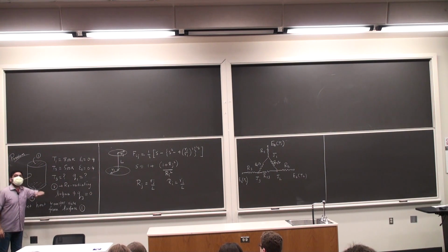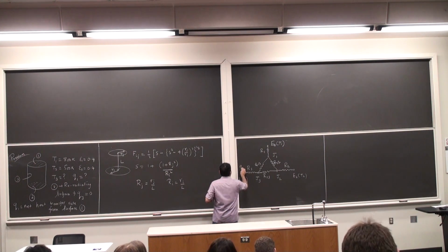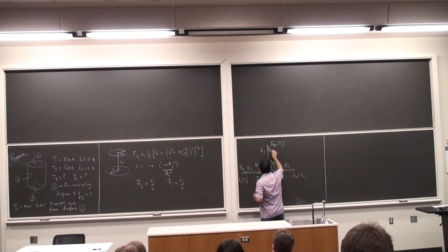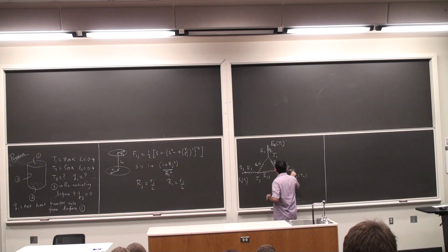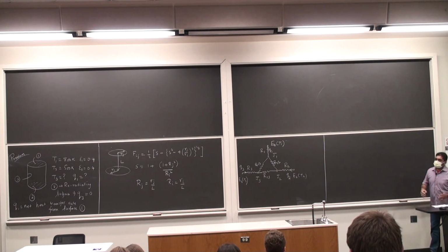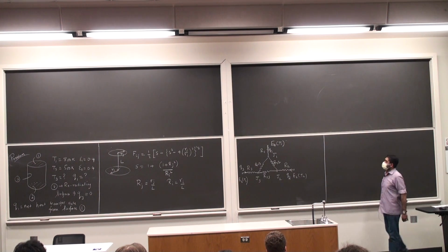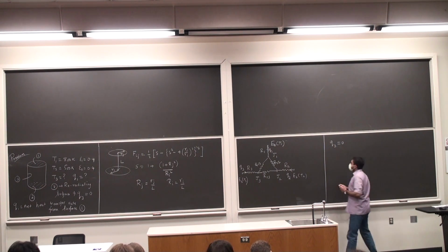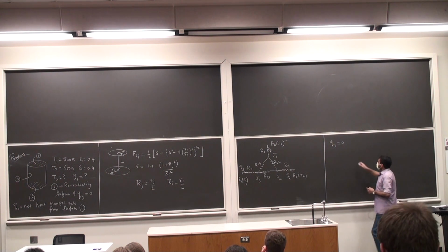First of all, notice that Q3 is 0. So Q3, typically if there was a Q3, that would start here. If there was a Q1, that would start here, and if there was a Q2, they would always start from the primary nodes. These are all the rates of heat transfer from surfaces 1, 2 and 3. The net radiative rate of heat transfer from surfaces 1, 2 and 3. Let's look at Q3. Q3 is 0. This is a re-radiating surface, or essentially the net flux on the inner surface is 0 for 3. So this tells me that